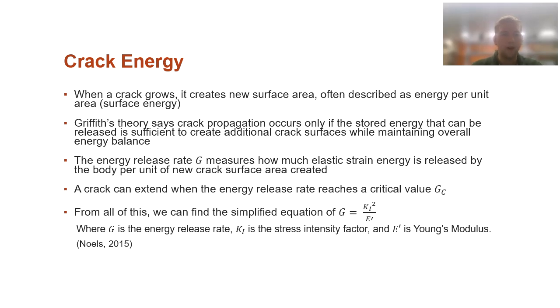And again, just to define another term here, we just talked about energy. It's important to know that when a crack grows, you're creating new surface area as that crack is opening. And we describe that as an energy per unit area, or surface energy, because it's the energy in the area, surface. Again, Griffith does work in this area and says that a crack will only propagate if there's enough energy in the structure to release and create new surfaces.